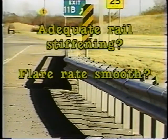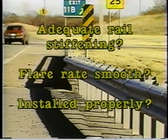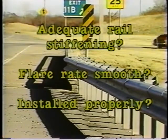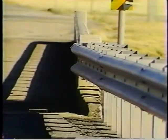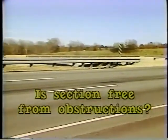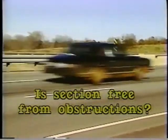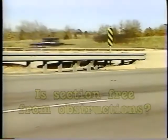Is the flare rate smooth and without projections that could snag a vehicle? Is the beam installed properly? Are the required extra posts correctly installed? Where weakness is present, a section of tri-beam rail may be needed to make the rail stiffer. Like the other barrier sections, see that the transition section is free from curbs, abutment ends, or other obstacles that might vault, snag, or tumble a vehicle.